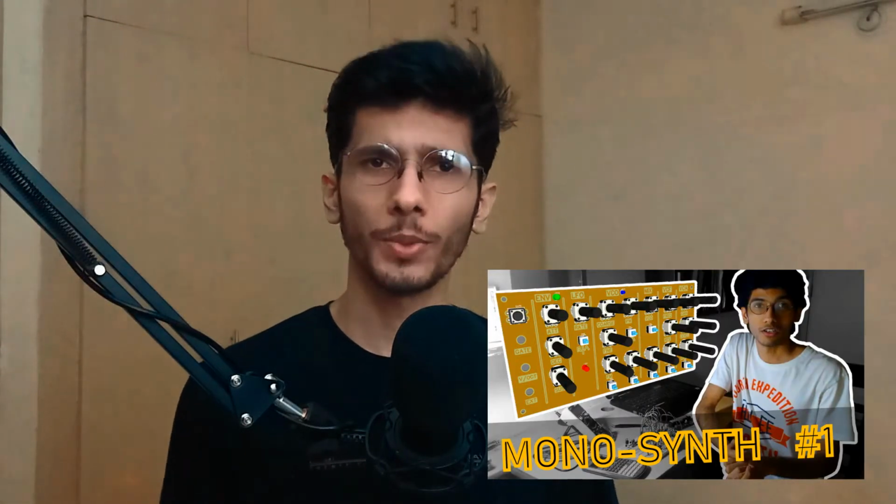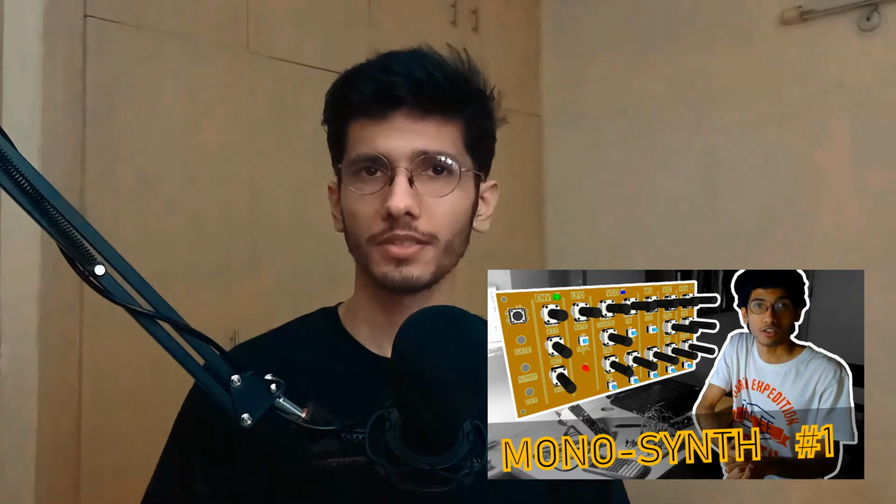Hi. So the last video just gave you a quick overview of the synthesizer I'm currently working on. This time I thought I would share a bit more and talk about the circuits involved, starting with the power supply. Almost all analog synthesizer designs I've ever seen use what is called a bipolar supply. So unlike a normal power supply which has two wires coming from the main supply unit, positive voltage and ground, a bipolar supply has three wires: positive voltage, ground and a negative voltage source.